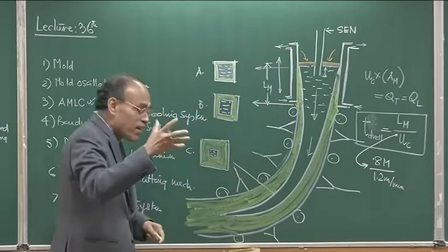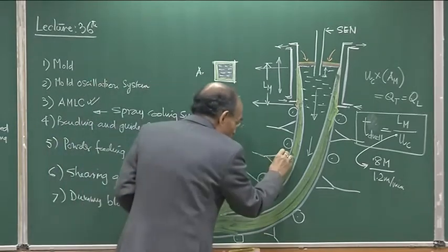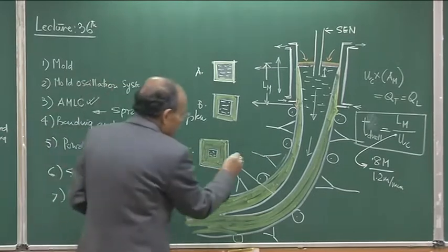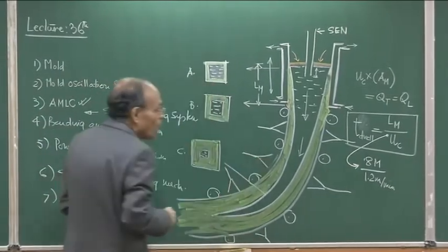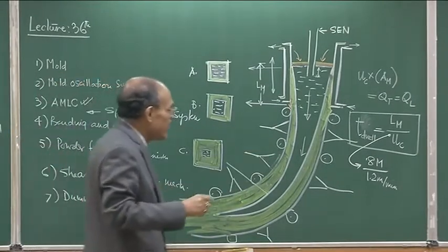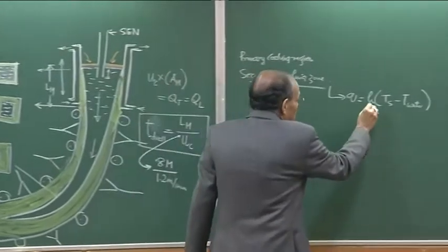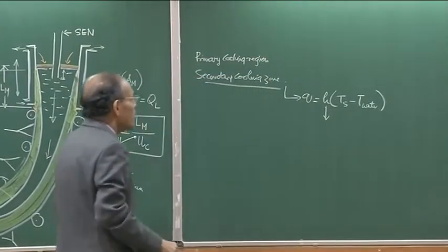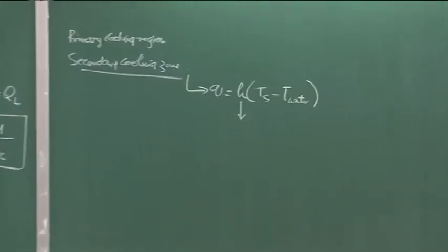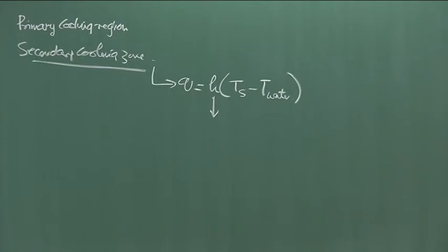These are air nitrogen, oxygen nitrogen mixtures. You have to understand the theory of pool and nucleate boiling in order to understand the mechanism of heat transfer. But nonetheless, this heat transfer coefficient is very large when you use air water or air mist cooling. Air mist cooling basically is an air water mixture jet, and that helps to create fine droplets, and the droplet surface area really makes the heat transfer coefficient very large.